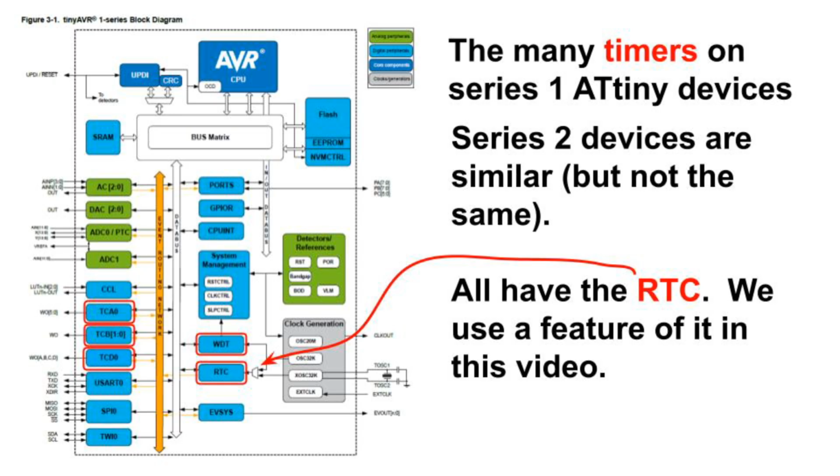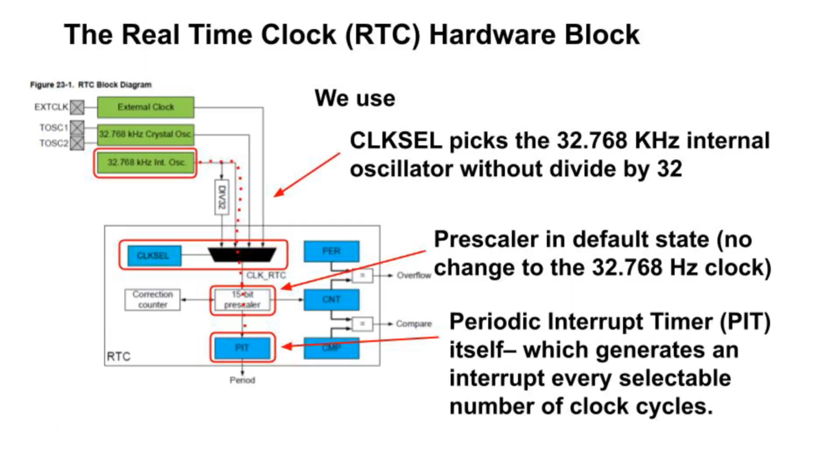Doing more with timers requires either libraries that provide further abstractions, or code that is specific to particular microcontrollers, that is, code that won't be portable. We'll show non-portable code today. We will use the timer called the Real Time Counter, or RTC. But we need only parts of the RTC block.